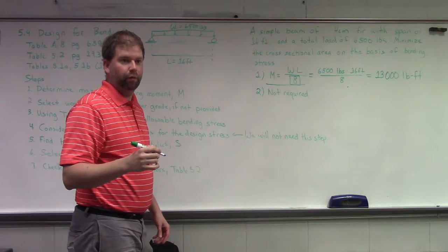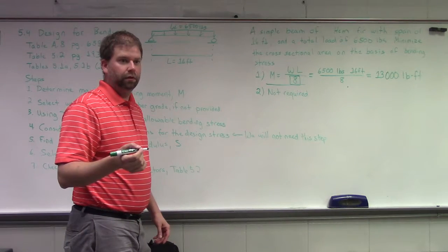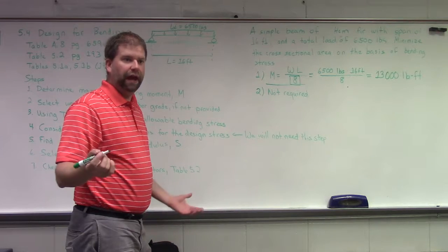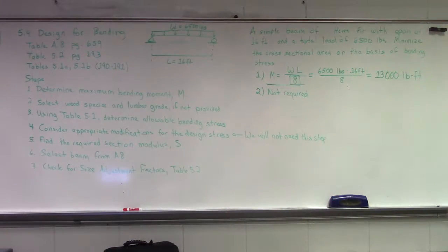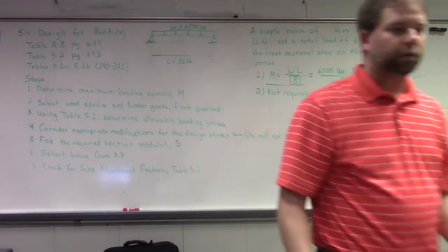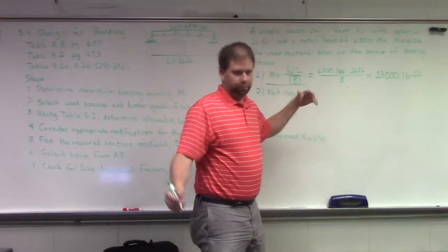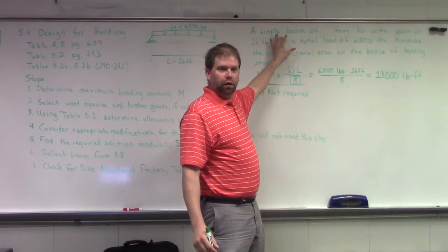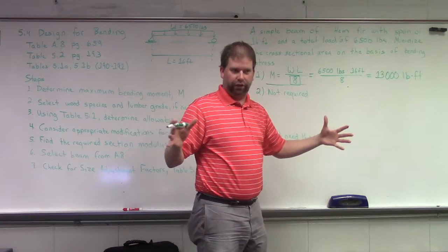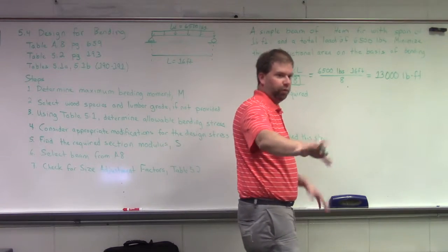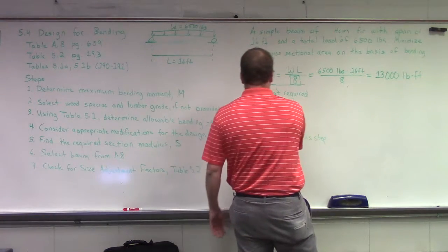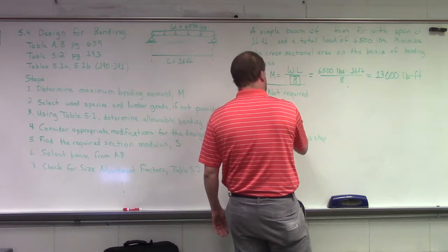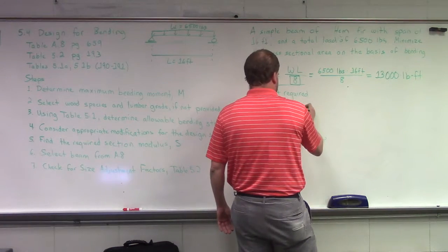Dimensional lumber says, why couldn't you use dimensional lumber for a beam? Oh, you mean just stacking a bunch of them together? If it's adequate, does it matter? Well, because it says beams and stringers right there, so I thought we were stuck to those. At least 2x4s for stringers. Right, but you could still use dimension lumber. I mean, we don't know what the whole tables are, it's up to us. We don't know what true construction is going on with this thing. But yes, we will also consider the select structural from the beams as well. I thought since it was a beam, we were stuck to those 4 choices there or whatever it was. Nope. All right.